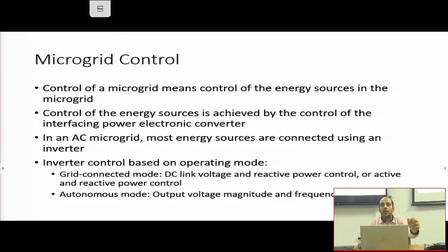For example, to control any home appliance, we change the voltage impressed across it. In the old era we used rheostats and potentiometers to divide the voltage. The better approach is to use power electronics. You have buck converters, boost converters, inverters, so you can play with the voltages the way you want. Once you can play with the voltage, you can get the desired result.